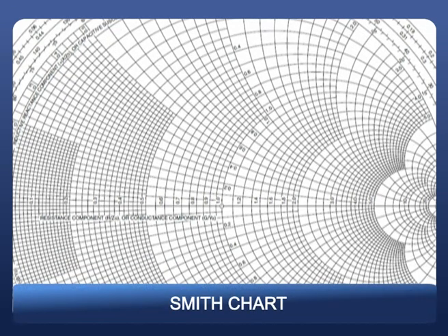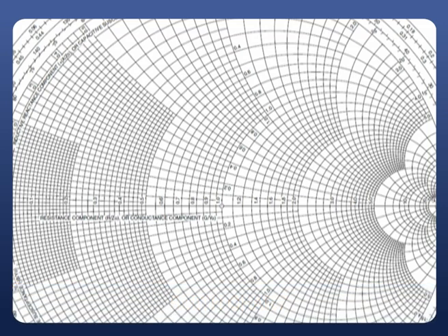This is the smallest circle that you are observing, and this is a little bit larger than that one. Like that you have different circles. All these are complete circles, right? These complete circles, clearly once again I am saying, are meant for a normalized resistance. And already we have drawn a few circles on our board: the exact center circle, which is passing through the center point, is meant for r equals 1.